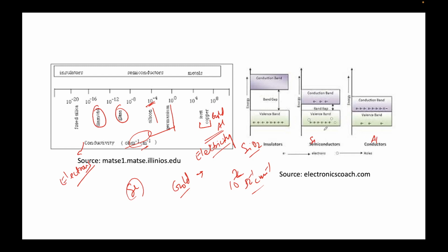Okay, so what is the difference between the two? You can see that the valence band and conduction band are overlapping. What it means is that if there is any electron here, it is free to migrate here. The conduction band is like a highway, and this is like your parking lot. So in order for current to conduct, electrons should be running on a highway, in either this direction or this direction. That depends on the electric field. If it's parked, it's of no use as far as conduction of current is concerned.